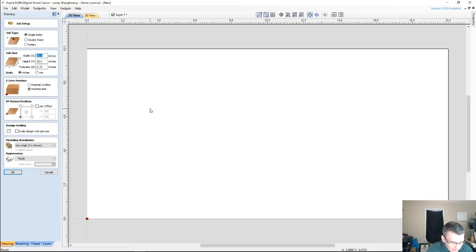What this is going to do is shorten the amount of lines of G-code that a design creates, thanks to the ramp movements versus incremental, and thanks to the new post processor. This will ultimately shorten the run times on a lot of jobs.